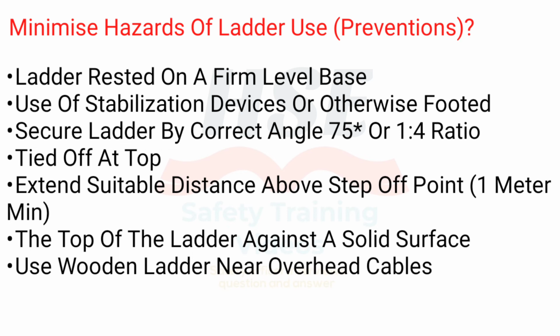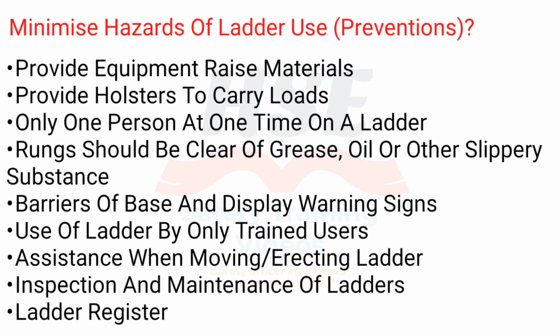Rest the top of the ladder against a solid surface. Use a wooden ladder near overhead cables. Provide equipment to raise materials. Provide holsters to carry loads. Only one person at a time on a ladder. Rungs should be clear of grease, oil or other slippery substances.